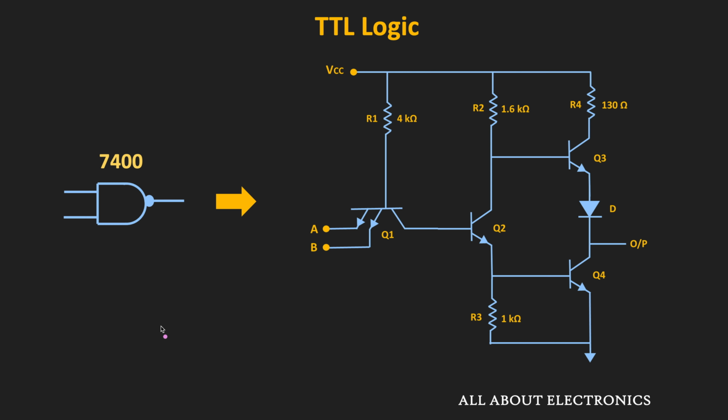So here, if you see the standard TTL logic or even the 74L and the 74H series, then in these series, the majority of the transistors in the circuit were operating in saturation. So in saturation, an excess amount of charge is stored in the base of the transistors. So unless this charge is removed, the transistor won't go into the off state. And that delay in removing the charge from the base of the transistor limits the speed of the logic gate.